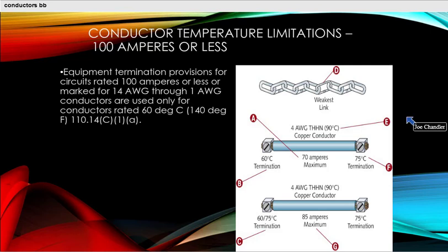Okay, this is the whole installation of a conductor and how we determine how much a conductor can carry. It all depends. Remember, a conductor is not just out there in free air, not connected to anything on each end. It's connected to something on both ends, and sometimes connected together many times throughout the middle. Each terminal point has an associated temperature rating.